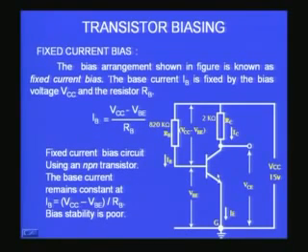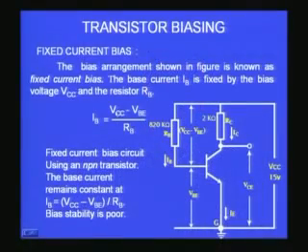In this case VCC is 15 volts minus 0.7 is about 14.3 volts divided by RB, which is 820 kilo ohm. So if you work out 14.3 divided by 820, this is kilo ohm, that is voltage. So with this kilo, you would find the whole thing will come in microamperes. So IB will be approximately a few microamperes. That is what this circuit is used to set.